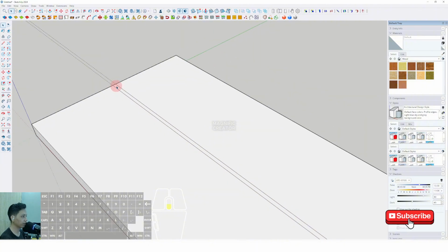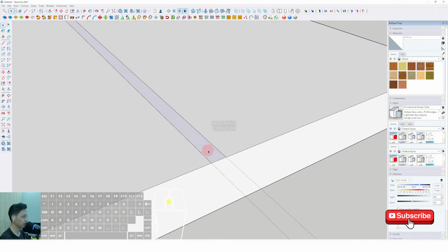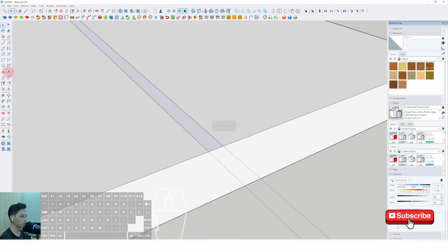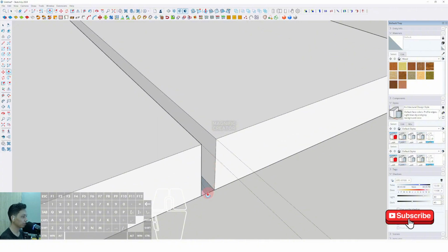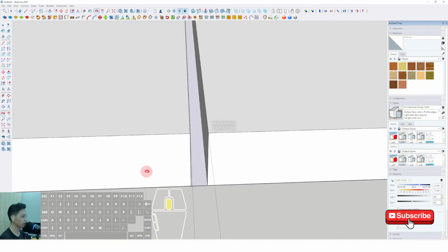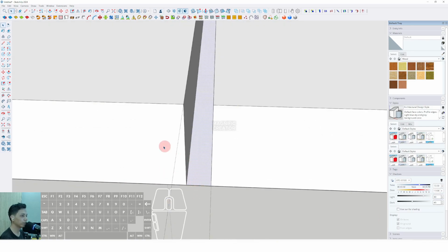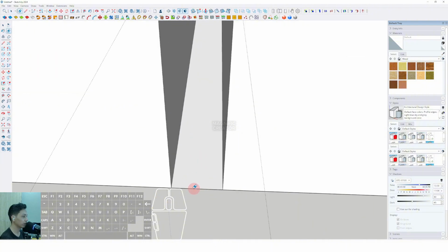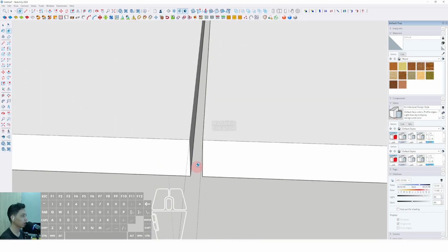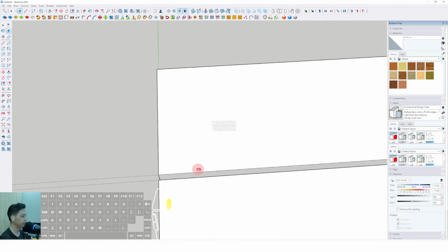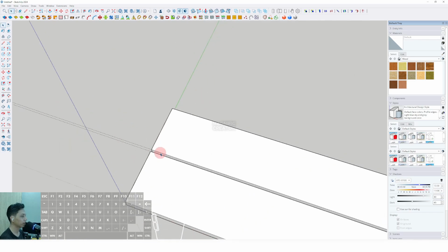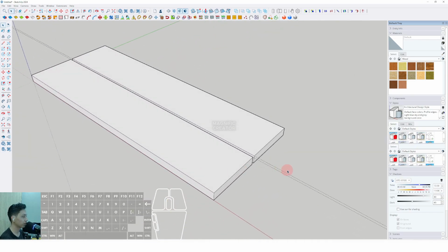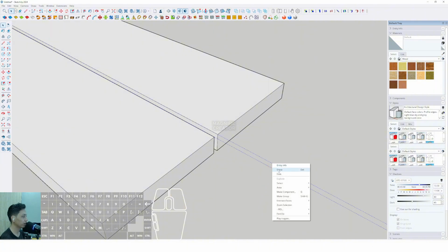and click this intersection. Okay, then we can click this little surface in here and select push pull and click the surface, and we can move it to the bottom until the limit like this. Okay, and it has been deleted. We have to delete this one with the eraser tool and just click on the edge so the plane is automatically erased. And also don't forget to erase this line also. Okay, then we can delete several guidelines here, right click and erase.